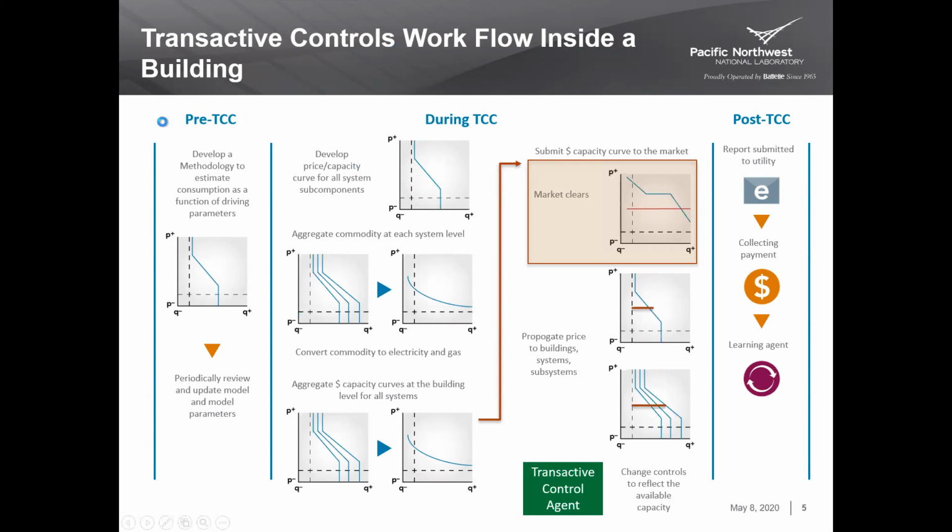That means that we would use some data, train the models, and then deploy TCC for some period of time, and then periodically review those models and update the parameters if needed. We've since developed an agent that allows for this to happen in an automated way, so that you can deploy this agent along with the TCC VAV agents, and it will automatically retrain the agent periodically and then communicate those new model coefficients to the agent.